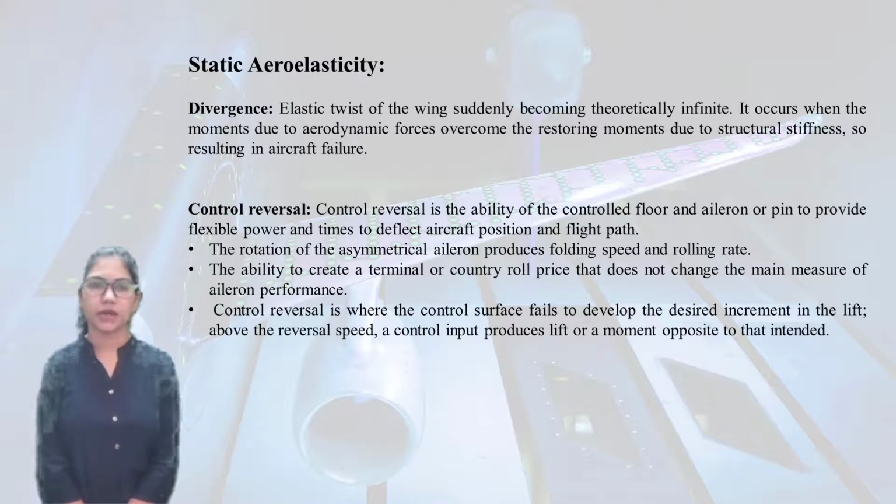The second phenomenon is control reversal. It is the static aeroelastic phenomenon that is contrary to torsional divergence. It does not cause the loss of stability but rather causes the loss of maneuverability. Control reversal is where the control surface fails to develop the desired increment in lift above the reversal speed. A control input produces lift or moment opposite to that intended.